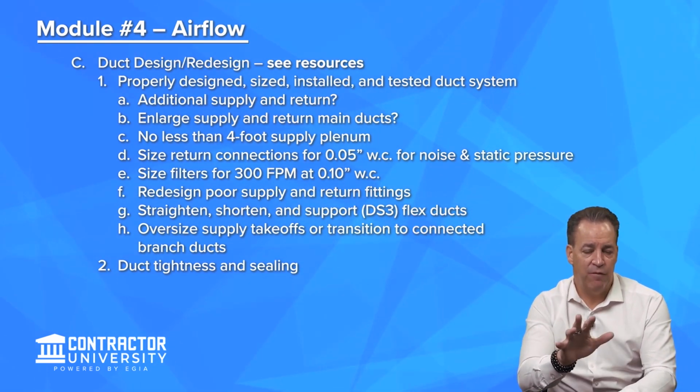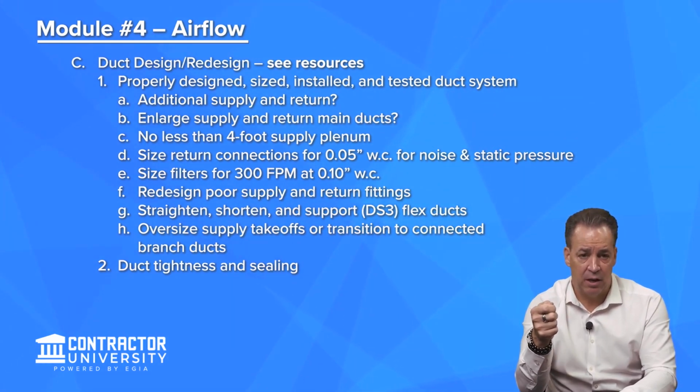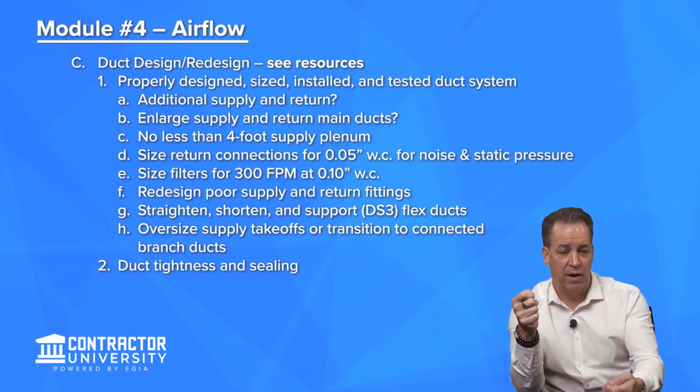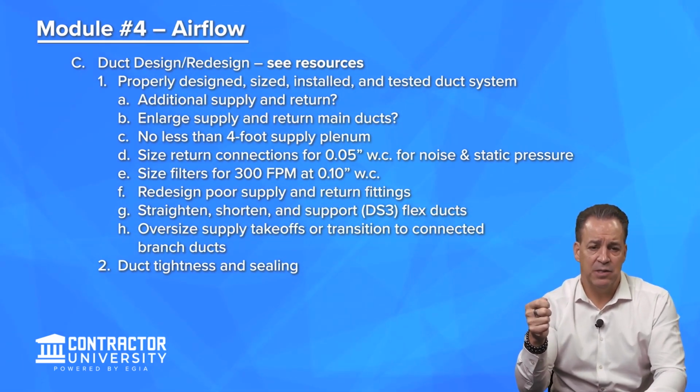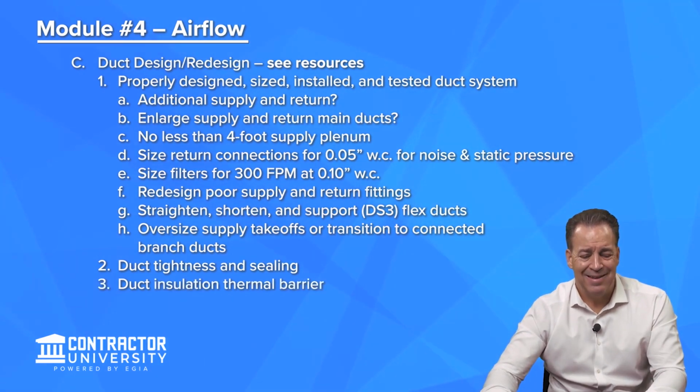I guarantee you will feel leakage there. If you can pull out the theatrical smoke, you can bring it to life and see it, and maybe even video it for a customer and let them see it if they can't travel with you up into the basement, attic, or crawl space. Duct installation and thermal barrier.